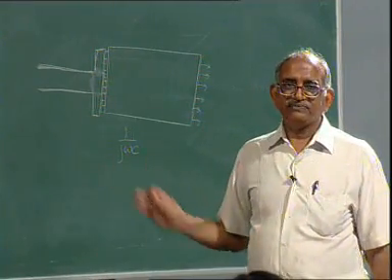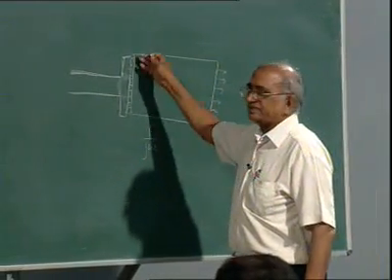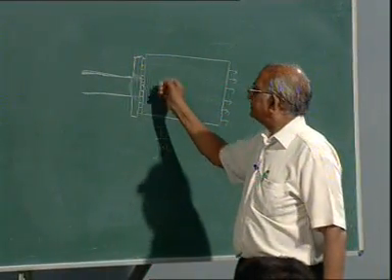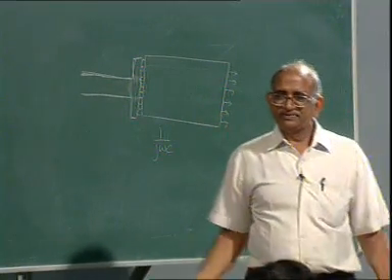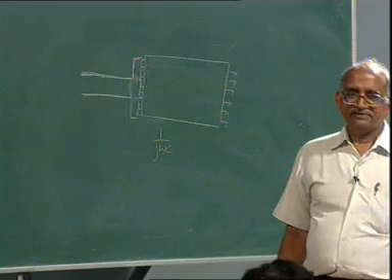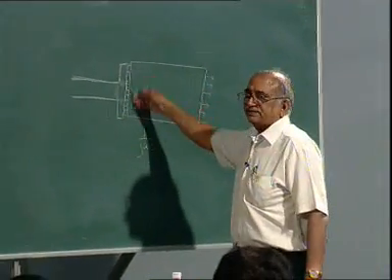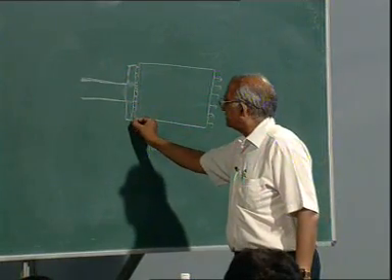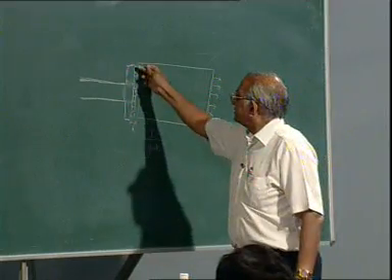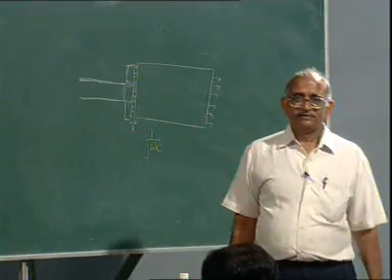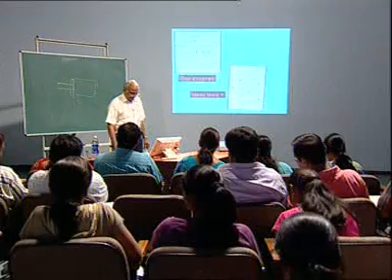So, try to maximize this capacitance, and this capacitance basically it is some sort of a parallel plate capacitance. It depends upon this dimension and the area, epsilon A by D. Okay. So, you want to maximize this area, that is, this is something like your comparable to your D, you want to reduce D, and this is your other dimension. Okay. So, this is the rule of thumb.